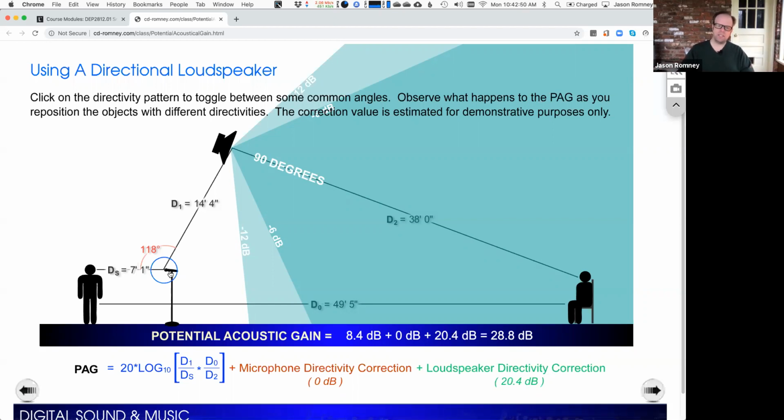In theater, we tend to not be able to leverage directional microphones as much because most often we're talking about wireless lav mics that are on an actor's head. Those tend to be omnidirectional because we can't always get them in the perfect spot. The perfect spot would be right here in front of their mouth, right? And if we can get it right there, then yeah, we could use a directional microphone and it would sound fine. But we tend to end up having to put it up here, or over here. And if it was a directional mic, then we'd be off axis of it there, and the frequency response would be all wonky. So we tend to use omnidirectional mics so we can put them anywhere on their head and it sounds more or less the same.